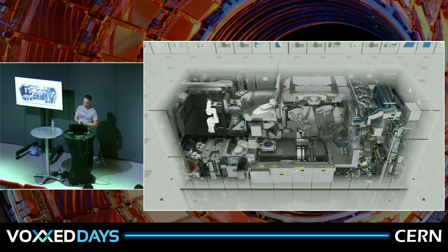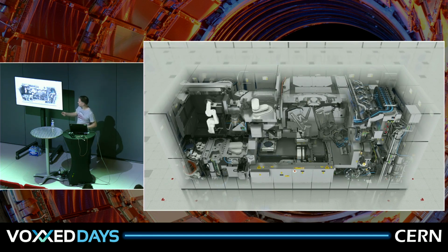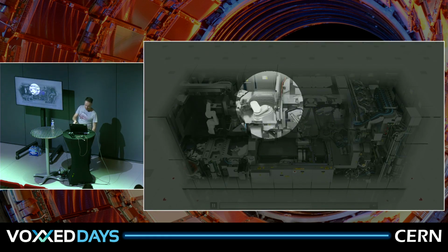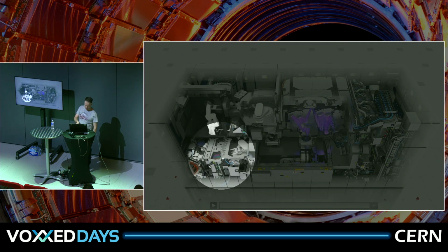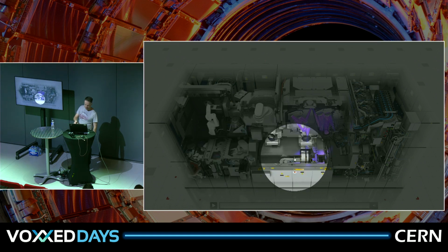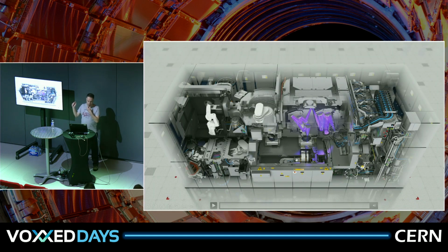And here you see the entire machine. At the top you see the reticles being changed, and here is the reticle. At the bottom we see wafers being changed, and they go in the machine there. So one wafer, I didn't explain that, it's about 30 centimeters in diameter, so it's not really huge. Before you also had smaller wafers, I think some companies still use them, but 30 centimeter was seen as the most economical and practical size, because if you make them bigger, again, it tends to bend a little bit, which again isn't really helpful for your chips.